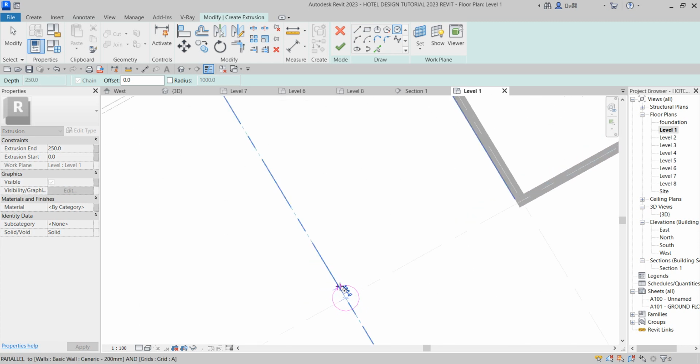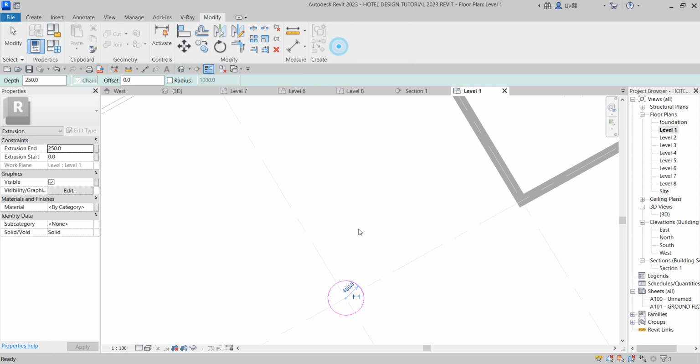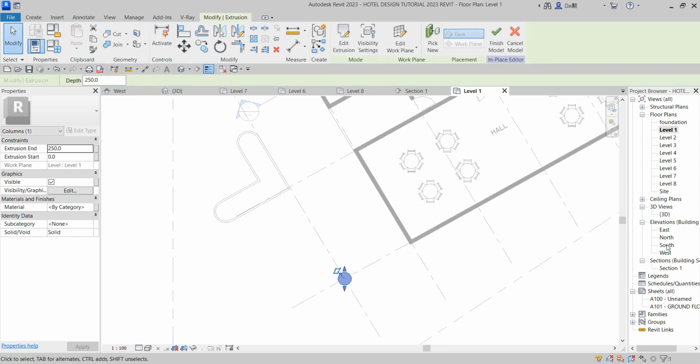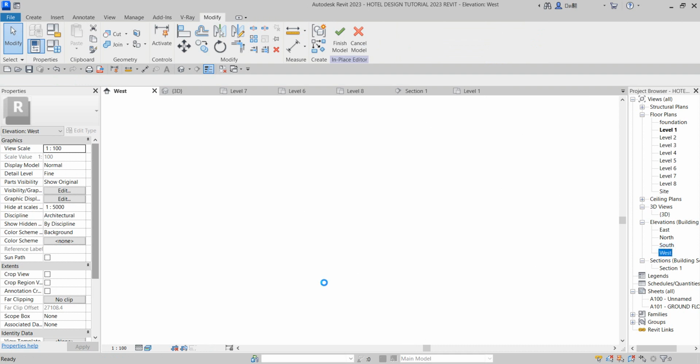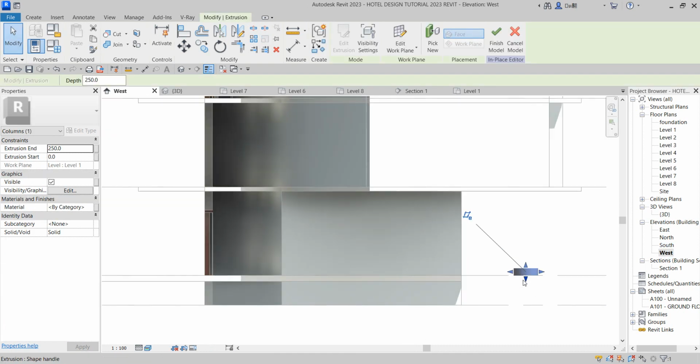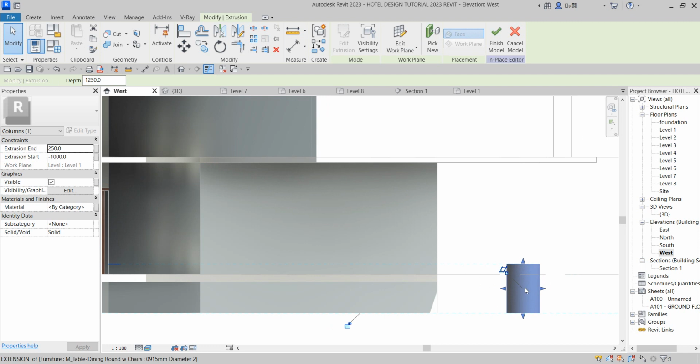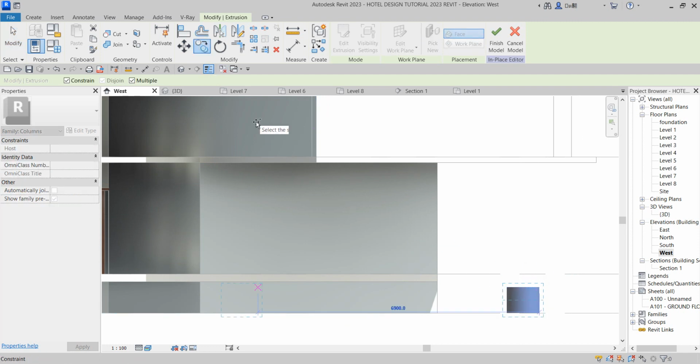So it's going to be a bigger one for the base. I finished that. So I will now go to elevation, anywhere I can find it actively. So I will drag it down and bring it to something that is okay by me. Then you click here and copy. You can copy while you are in the mode, but when the thing is giving you constraint level, click on constraint like this. It will just detach itself from that constraint aspect. So click here like this.